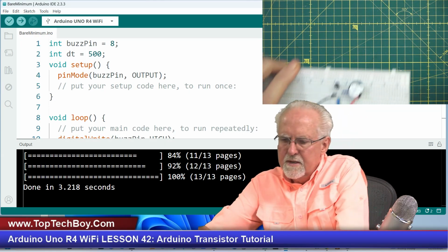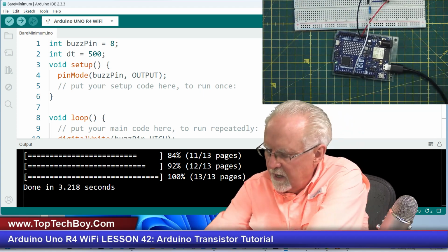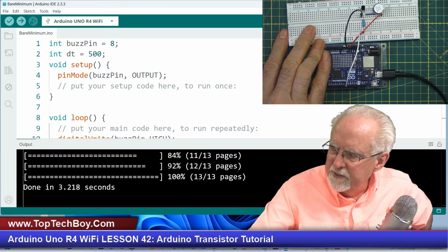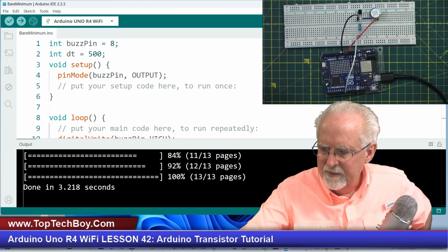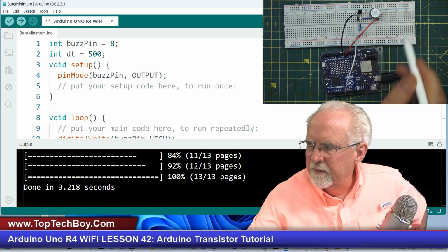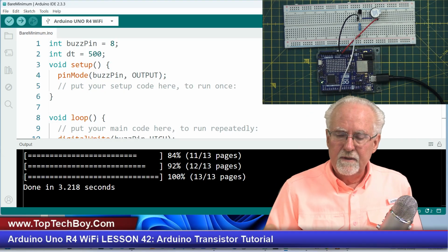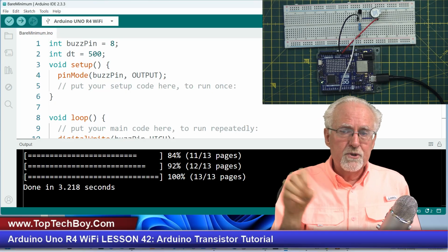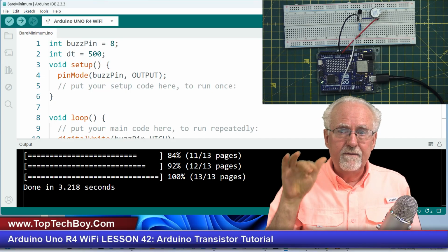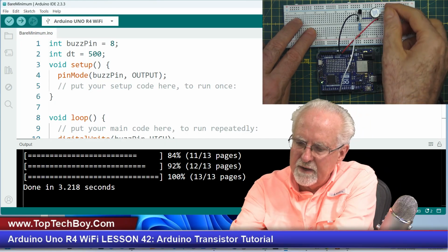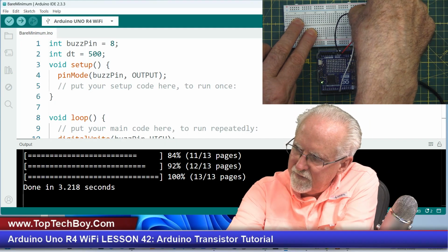Okay, do you hear it? All right, you can see that it's not very loud. So what I'm going to do is show you guys a pro tip. Do you see this label on here? The purpose of this label is that after they have made the device, they have that label so they can wash it without the cleaning fluid getting down in the buzzer. But after it's washed, it's not needed, so we can take that off.